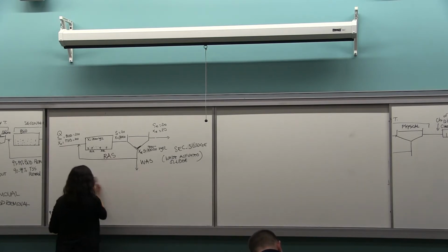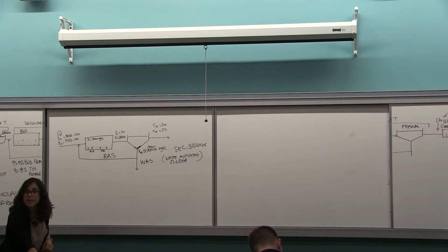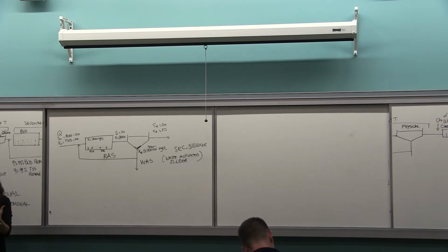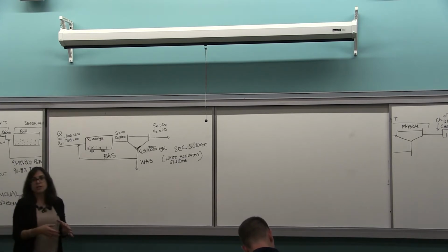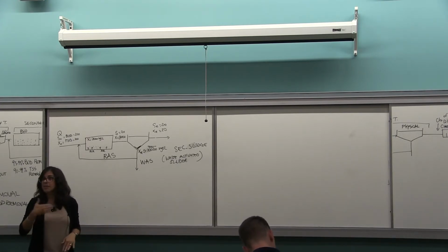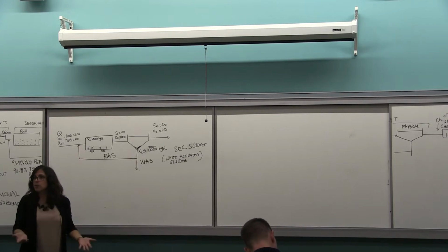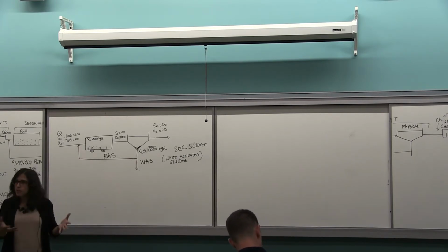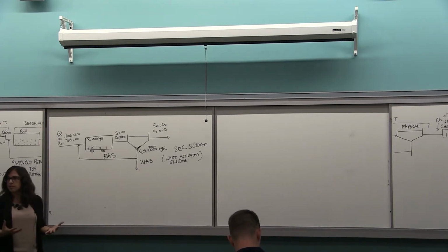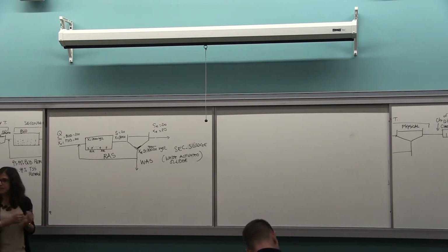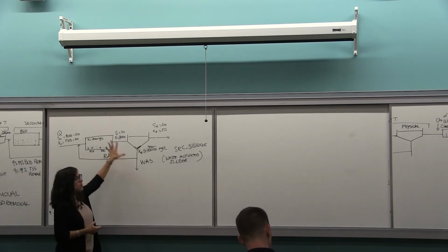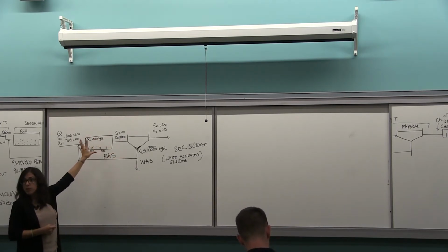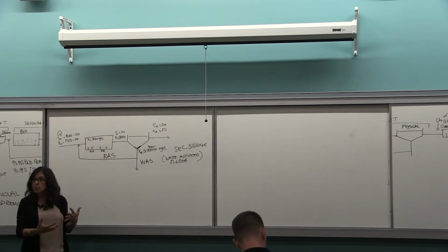Are these bugs organic or synthetic? It's organic. The bugs are already present in wastewater. There are millions of bugs already in wastewater, so you don't need to add any bugs. At the beginning of the plant, when you design the plant, it will take some time to get the right concentration. So there will be a transient time to build up the population so you don't waste anything. But after a couple of weeks of operation, you would achieve enough bugs there that can sustain the process.